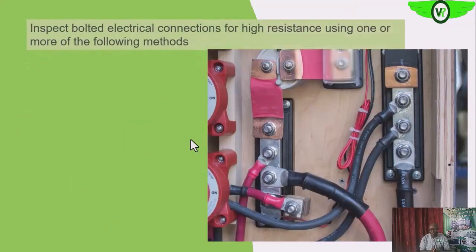So next, what we need to do is to look physically at the connection points, whether there are any visible signs of high resistance at those connection points. Those visible signs could be metal oxides, those whitish or greenish substances deposited on the conductor at this particular terminal point, where the cable is terminated. If there are those metal oxides, those are clearly signs of a high resistance point.